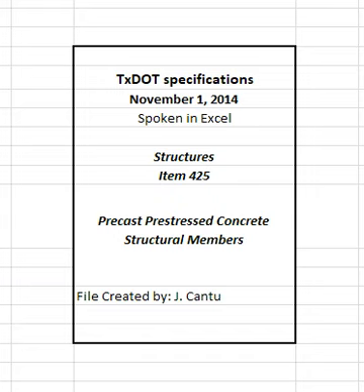Do not move members from the casting yard until all requirements of the pertinent items have been met. Haul beams to the project site after at least 7 days have elapsed since casting unless otherwise approved. The storage area must be clean and well drained. Prevent excessive or differential settlement of members by storing on stable ground and dunnage of sufficient size, shape, and strength to prevent crushing. Place dunnage a distance no more than 3% of the beam length from the beam ends. When approved, cantilever beams may be supported at locations other than near the ends.